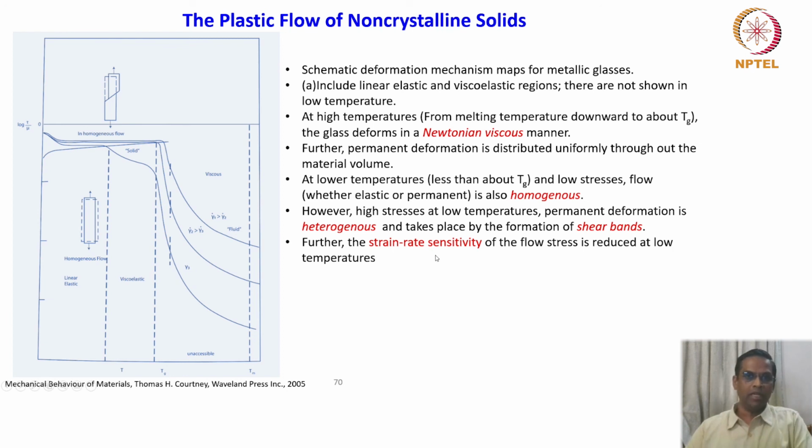Obviously, we have already seen in high temperature deformation that the strain rate sensitivity M is almost equal to 1, which is Newtonian flow. But at low temperature it will obviously get reduced.